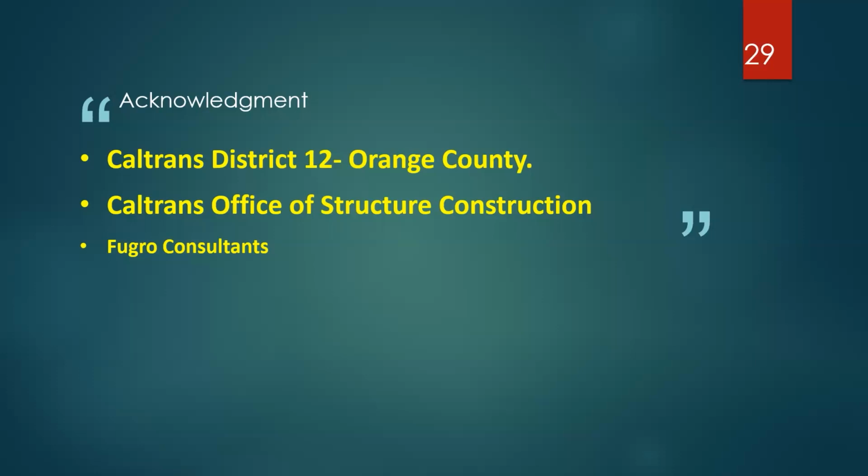Okay. Another thing that came up was obviously with CPT, you have your continuous profile. So in a way, you are doing more testing, not just at specific points, but to get a continuous profile. Do you think that because of that, some liquefiable layers were identified that you would have otherwise missed and would have had an impact on the design of the foundation itself? Yes. So the question is, if you would not have done CPT, is that what you're saying? Yes, absolutely. And that's what I think I alluded to earlier.